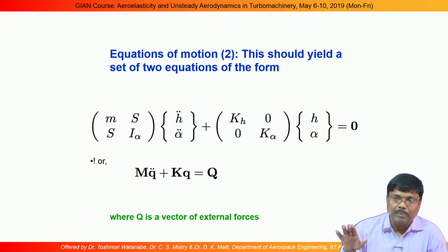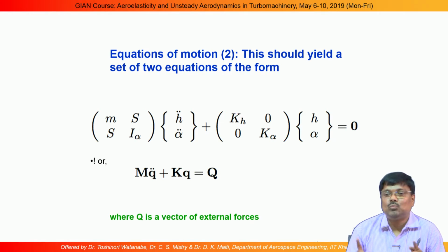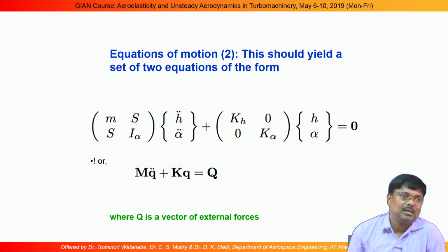When there is no damping, if we express in a vectorial representation, we will find that the damping force is not there, these two forces align together, and we can normalize the system with respect to our modal vector. That is why we call it the normal mode analysis, but we can take damping also.